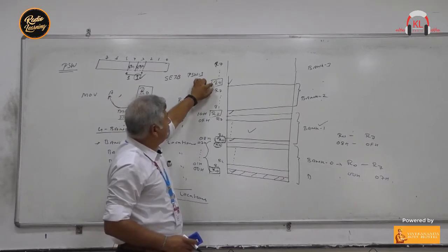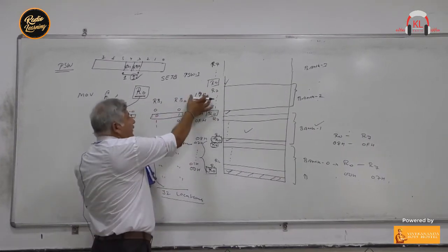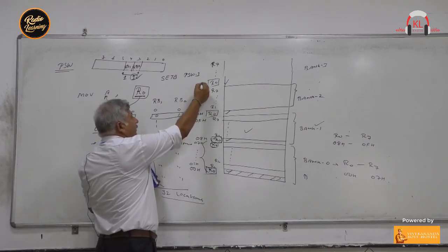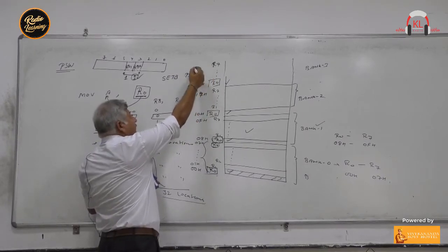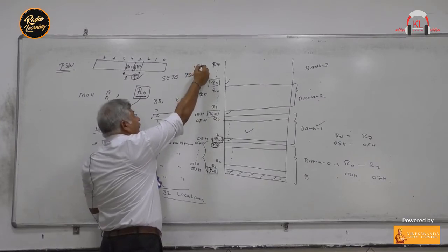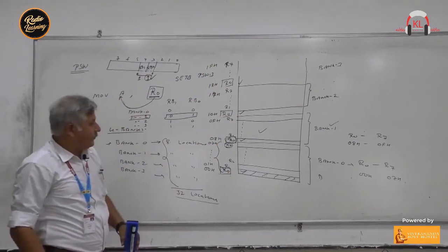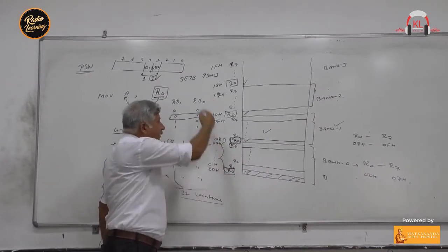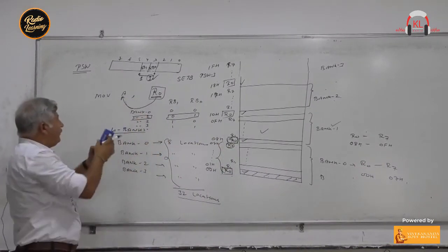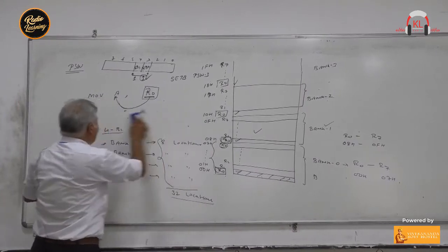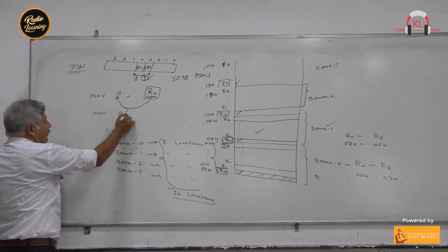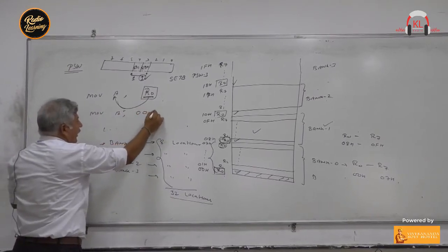Now the R0 register of bank 3 will have the next address after 17H. After 17H, the number is 18H, and the last register R7 will be 1FH. These are the addresses. So we can access these registers by name or by address also, right? In the same way, for example, in this instruction, in place of this, I can write this also: MOV A, 00H.